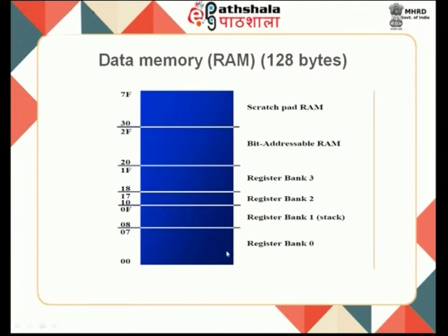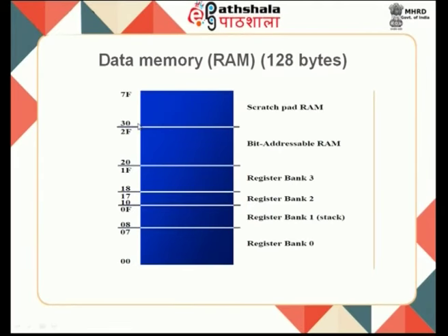I can say that 00 to 1F will be reserved for your registers. You cannot use it for storing your data or any program, whatever be the thing, you cannot store it over here. It is best you use memory from 30 to 7F, because these are all reserved spaces which I should not handle.